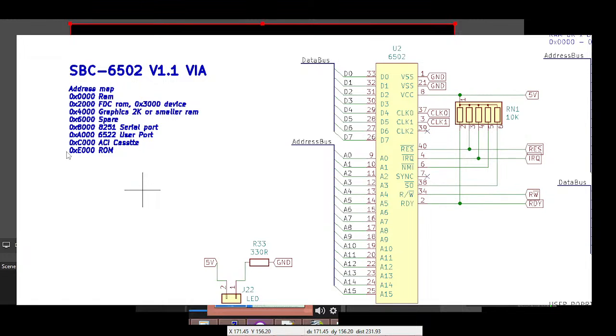The most important part is our ROM. That's where ROM is being loaded in on the memory. Our RAM starts at 00, and what we're planning to do is, where the ACI for the Apple II was, which doesn't work on my 6502 for different reasons, we'll put the ROM BASIC there. Let's just edit this. So we'll put RAM part 2.